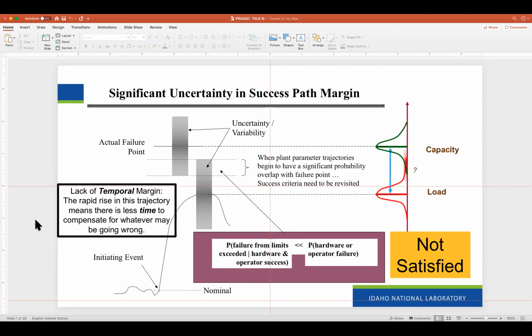And they actually did a sensitivity study where they added a basic event corresponding to the left side of this inequality. Like the equipment worked, but the core still wasn't cooled. To see how much difference that basic event made, I think they put in a 0.1 or something, and I'm not sure I approve of what they did with the result. The result was that the overall bottom line didn't change very much, because from large LOCA they weren't getting that big a contribution anyway.